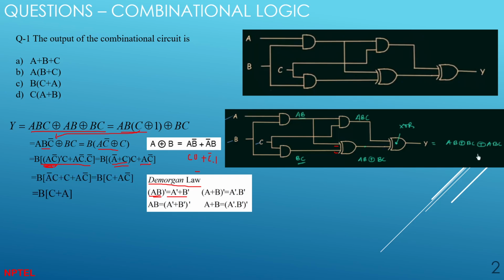In this manner you can solve this kind of question, but you need to know the formula. And the other way is you can make a truth table, right? With A, B and C, and then there is a Y also. You can make every combination. There are three variables, so 2 to the power 3, that is 8 combinations. For the 8 combinations you can get some value, right? But I think here Y is given or not. If Y is given, then you can do it. But if Y is not given, then you won't be able to do it.